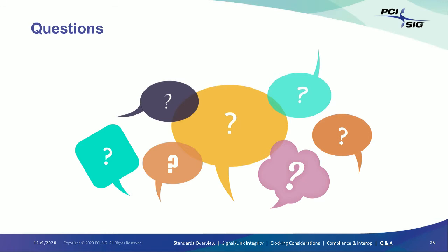As an example, if a receiver relies heavily upon DFE TAP 1 in its architecture, it may choose to request pre-coding to be enabled during link training because, as we mentioned earlier, when DFE is heavily utilized in equalization, that makes a receiver more prone to burst errors. So each receiver will make its own determination based on its architecture, and then it will request that from the link partner accordingly.